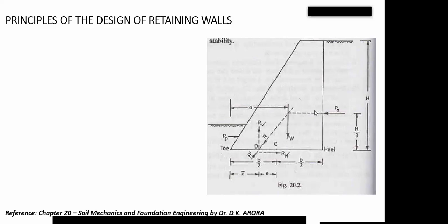As it's meeting the vertical weight of this retaining wall, they're going to meet at a point. Now I can extend this out. Don't forget the arrow keeps on going, so I can keep extending. From your knowledge of resultants, it's very clear that the resultant effect of your lateral pressure and your weight is going to go along this direction. Just follow me. This may seem very unreasonable now, but it's very important. It will give you a proper understanding of our design.